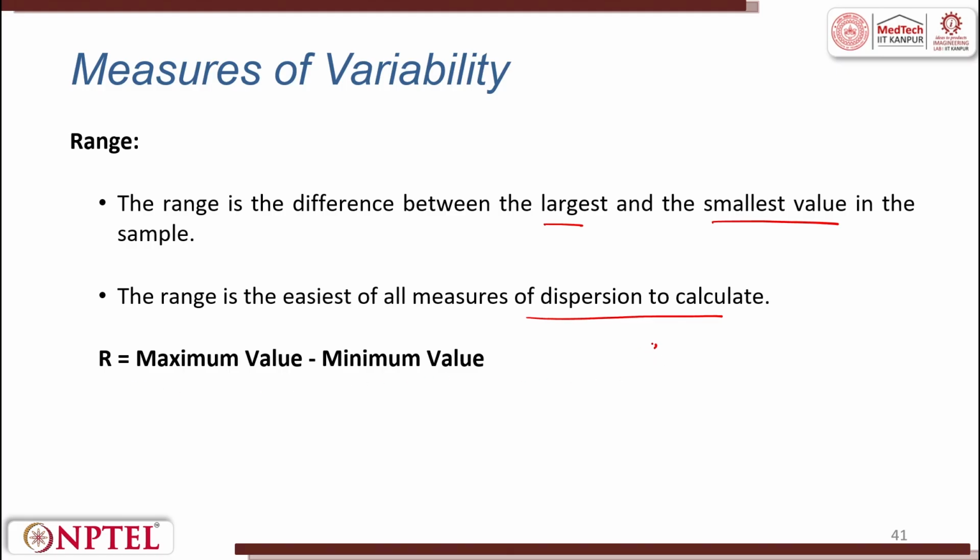In SQC, that is statistical quality control in manufacturing, when we try to see whether our output, or the performance of the boiler or the turbine that is running, is within control or not, we plot a chart. For variables, the chart is known as the X bar and R chart.